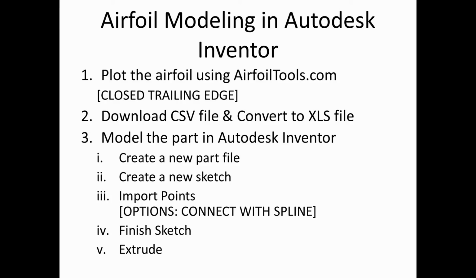Hello everybody, today I'm going to show you how to model an airfoil in Autodesk Inventor. We use airfoiltools.com to generate the airfoil points. Make sure you tell Airfoil Tools to close the trailing edge. It'll save you some trouble later. You won't end up with a hollow part that you have to fix by hand.